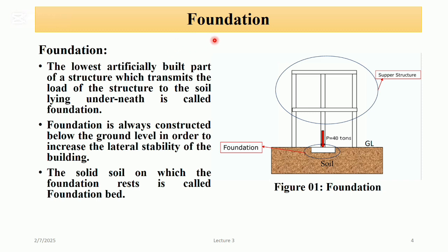Let's discuss the concept of foundation. The structure, such as piers and walls, is subjected to the load of floors and roofs, furniture, wind and others. And then the load of the walls and piers is transmitted to the soil on which it rests. The load thus acting on the soil is to be distributed over a large area so as to bring the intensity of the loading within the safe bearing capacity of the soil.